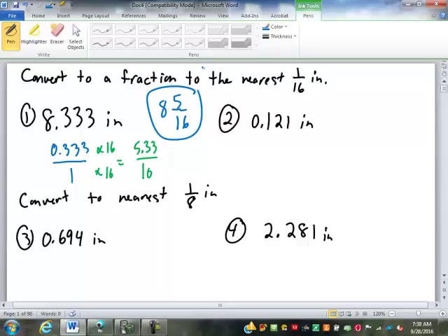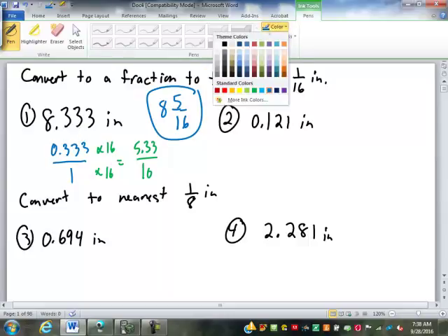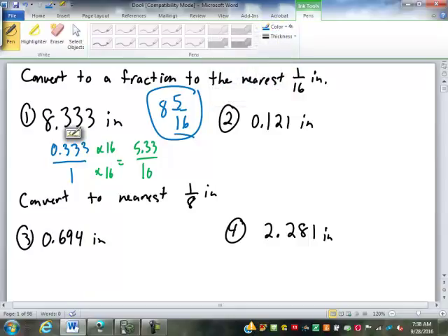Yeah, you got to get it to the 5 sixteenths. Well, I mean, if you had it as 3.125, okay, that's fine. We're converting it here because that's the tool size you'd be looking up if you're pulling a standard tool out to make that hole or whatever it is.